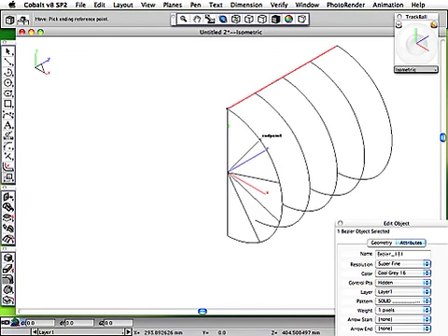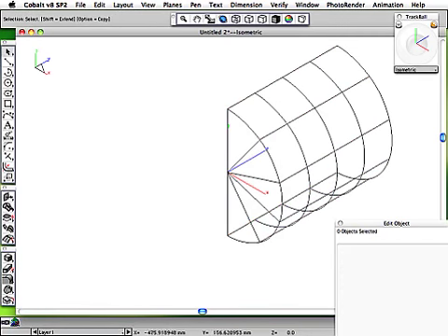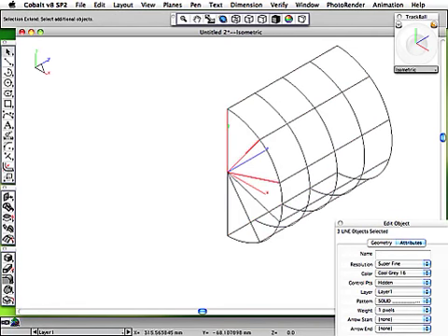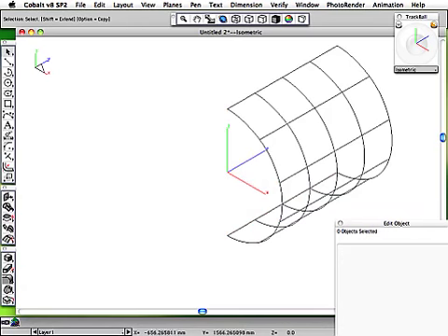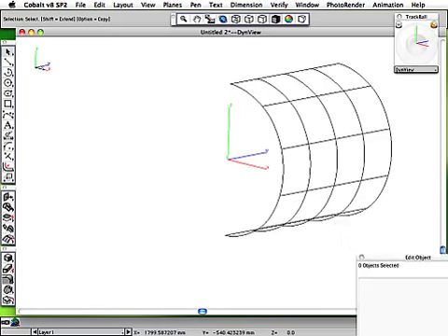Now I'll copy that spline to the other end points. Didn't go, still got it wrong. There it is, last one. Now I have 2 sets of splines that will be used to make a net surface. And because their control points are intersecting, if I grab on any of those intersections, I'll be able to distort the surface.